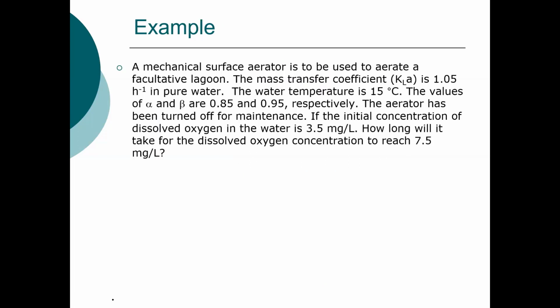Okay, so we can do an example here where we have a mechanical surface aerator, and we're using this to aerate a facultative lagoon. The mass transfer coefficient, KLA, obtained from the manufacturer is 1.05 inverse hours. The water temperature is 15 degrees C, and the values for alpha and beta are 0.85 for alpha and 0.95 for beta.